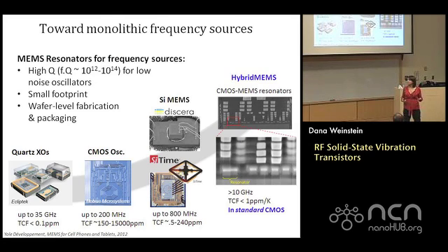But there are two ends of the spectrum in terms of frequency sources that you can get today that can be relatively easily implemented in large-scale consumer applications. On one end of the spectrum, we have quartz crystals. Now, quartz crystals are fantastic. They're basically crystal elastic wave acoustic resonators. They're piezoelectric. I apply a voltage across this crystal, and it strains the crystal, and I can do it at a particular frequency to generate a standing wave.